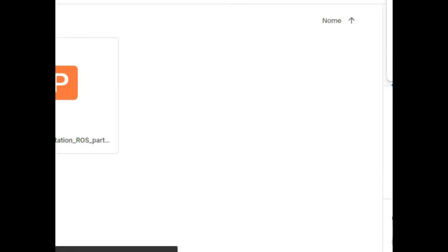We have the behavior planning that switches between the global and the local planner, and each sensor here is closely related to a function. So as we said in the implementation I have done in Autoware Auto, the camera is responsible for lane detection and traffic light, but the GPS is more used for the localization task, for example.